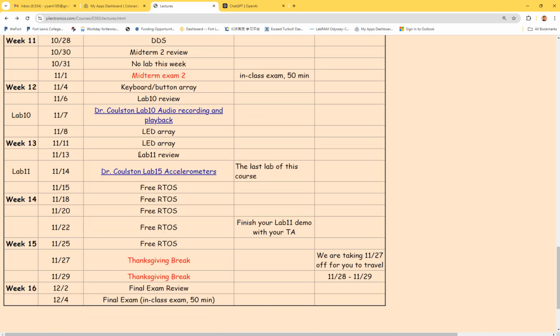The last one I picked for you guys is the accelerometer, because that one is super practical. In the future, people are building robots and all these kinds of sensors, motion sensors, and this is the one you want to use. It's low cost, and it's called microelectromechanical systems, MEMS. It's a really popular research area where I can build microstructures with silicon and sensors into one integrated circuit chip. And that single chip can give you results of acceleration and the gyroscope, which is angular velocity as well. Really useful and practical example.